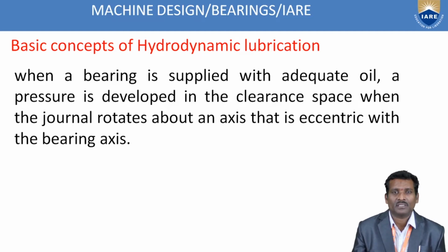Eccentricity means the radial distance between the shaft axis and the bearing axis. There is some distance, a gap, between these two axes. Only then is the clearance possible inside the bearing, and the lubricant fills up this gap, and further sufficient pressure will develop. Without this eccentricity, the lubrication mechanism is not possible in hydrodynamic lubrication bearings. There are many stages, and we will see what happens at which stage in this